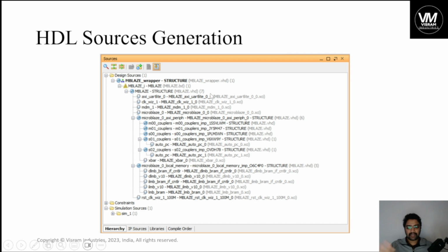So architecture on the controller, system reset or debug module, any other thing. So you can see all these AXI peripherals that have one VHDL. All these VHDLs of individual blocks are attached as a single larger file. So that is what we call a wrapper.